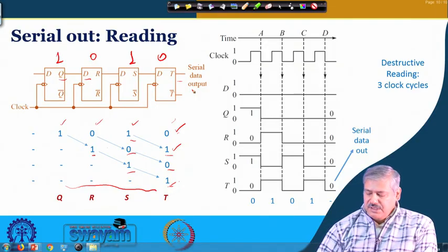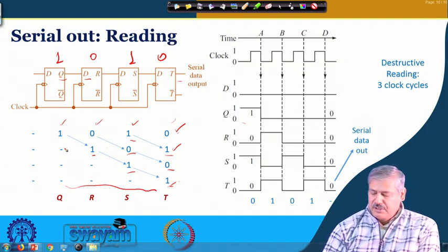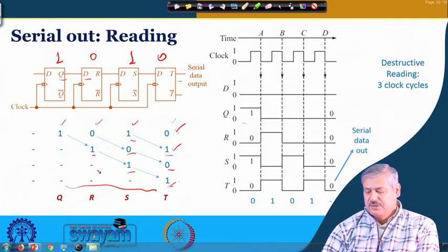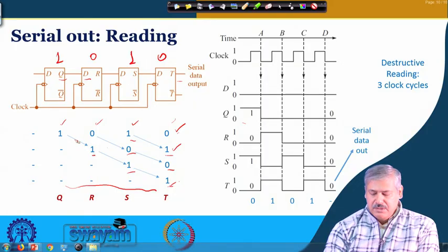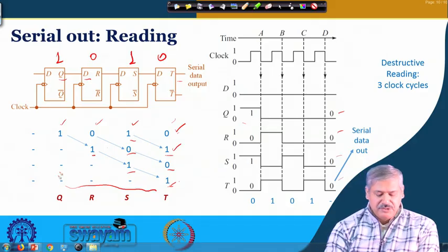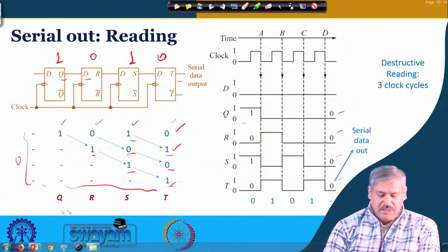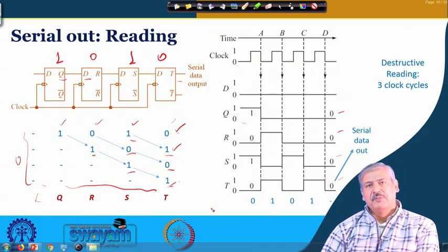Okay. And this is shown through the timing diagram. Okay. So, in this case, this 1 0 1 0, you can see this is the way, and if you are inputting 0 at the input side, then finally the values will become all 0. If all 0 is being inputted over here, then with one more clock cycle, all zeros will be coming.